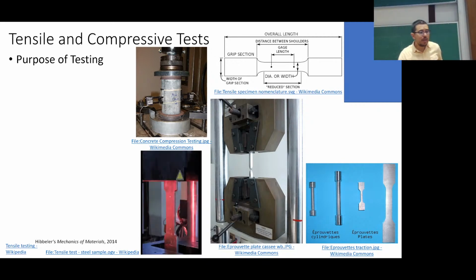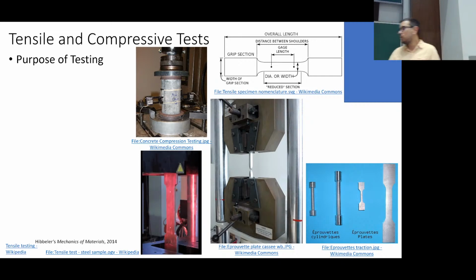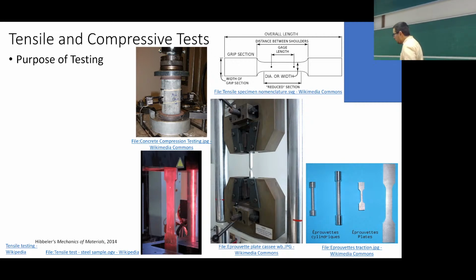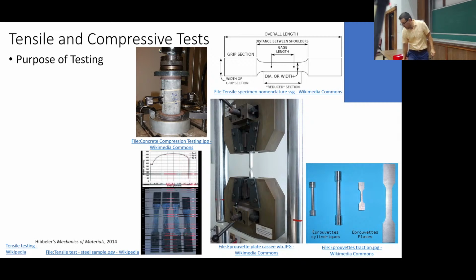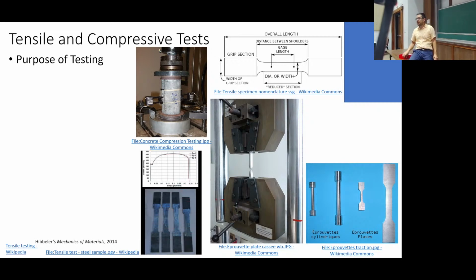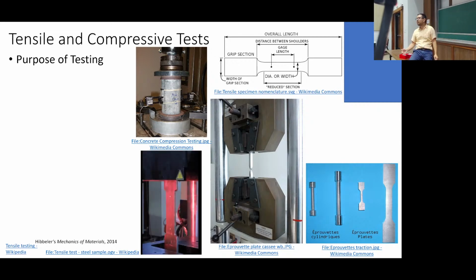So if you go back, we talked a little bit about this, I think maybe the first time we met, that there are properties of structures. Like, I can give you the stiffness of this table, and maybe it's, I don't know, 10 kilonewtons per millimeter in this direction when I sit at this location.